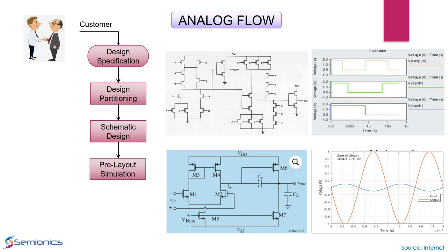When a circuit designer is doing these things, they do not have physical information. They have the model parameters of how each and every transistor or resistor behaves, and based on that, they arrive at a conclusion. Once the design is done, the designer verifies whether the results are met as per the specifications. If not, the designer tries different techniques or plays around with the W by L of the devices, or whatever parameters, until he or she meets the required results. Once it is met, it goes to the next phase of designing.